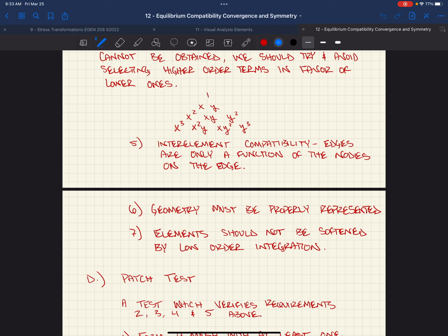Yeah, because you're losing a contribution along the length based on another term. It's a way higher order term, so you're not going to add as much stiffness, but you're still losing a contribution. So at x equal to 3, your displacement based on your cubic might be 1.2. Well, if you used a polynomial to the fourth degree, it might be 1.21, right? It might have displaced more because you lost a contribution from one of the terms. It's really a fourth order polynomial, not a third order.